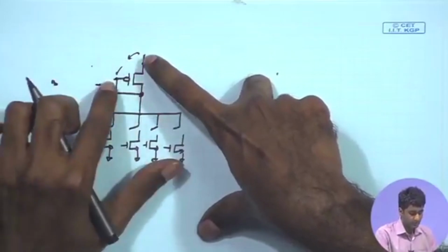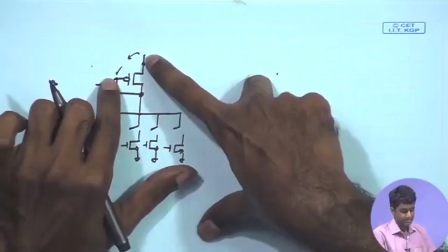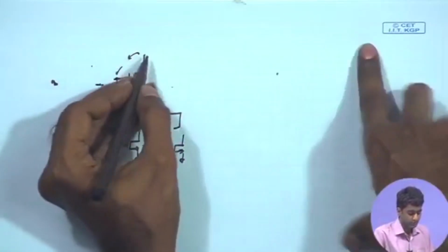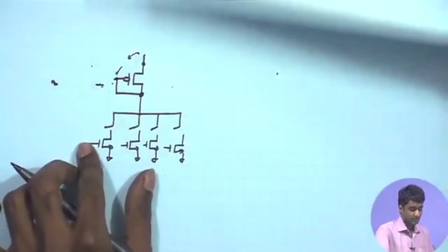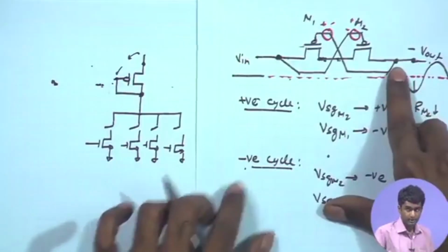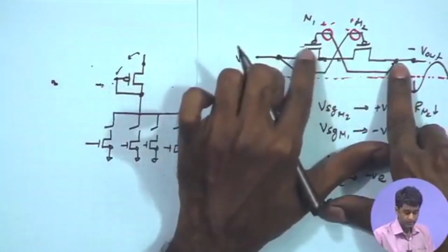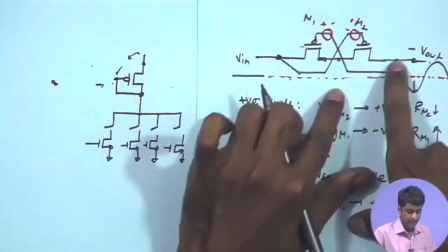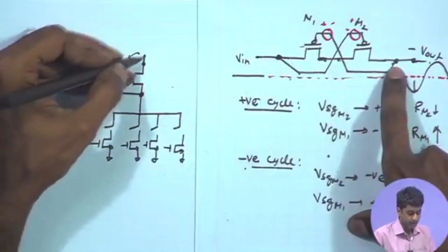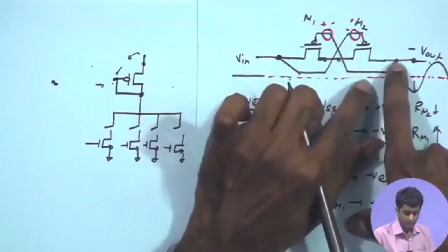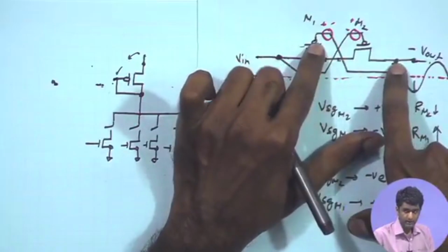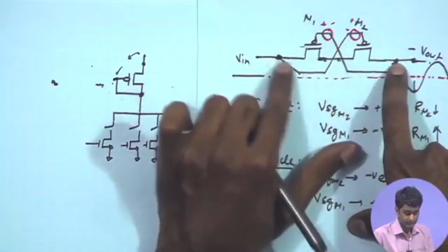Basically, the voltage developed across the source and gate of this PMOS can be used as an effective battery. Basically, we are going to connect this particular source terminal, for example, at the output point, and the gate terminal will be connected to the gate of the MOSFET. So, that as compared to the output point, we are having a VSG drop between this point and the gate of the MOSFET. Likewise, for the other side also we can do the same.